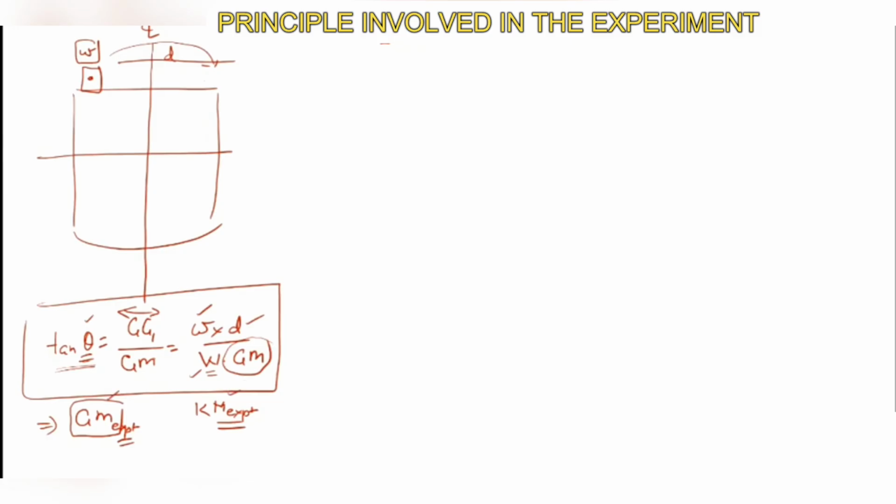I am sure all of you know that this GM that you obtain will be GM fluid, because when the list is caused, if there are any slack tanks, the liquid will also flow. So we'll evaluate the tank conditions of our ship when the experiment is performed, find out which tanks were slack, and find out the FSM of those tanks, which gives us the FSC in the experiment condition.